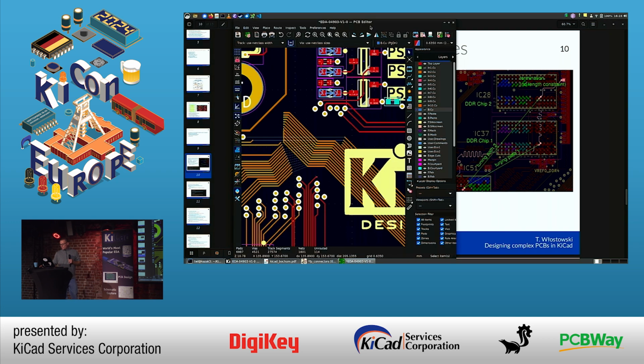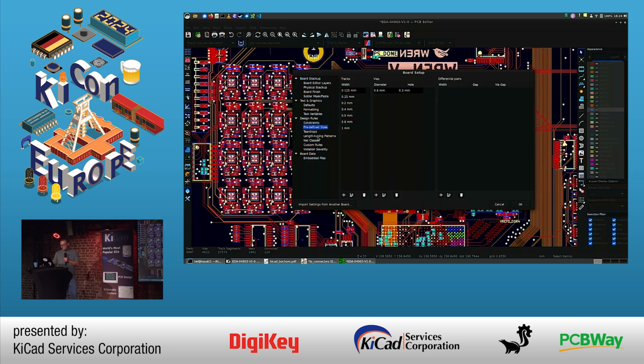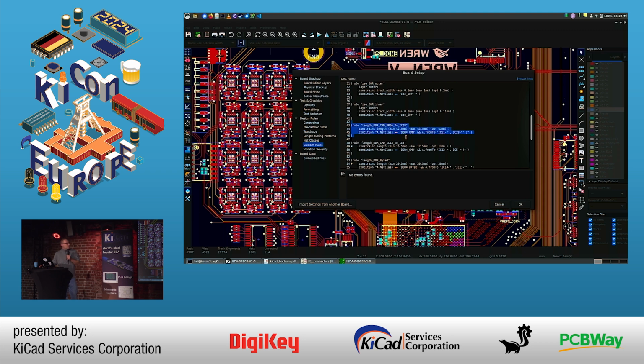I'm not sure this will work well in a development version of KiCad because I might have broken something, but nonetheless, let's have a look. Custom rules. Yeah, so this is our rule. Let's say our target is 43.5 millimeters. No, 43 with plus minus half a millimeter tolerance.